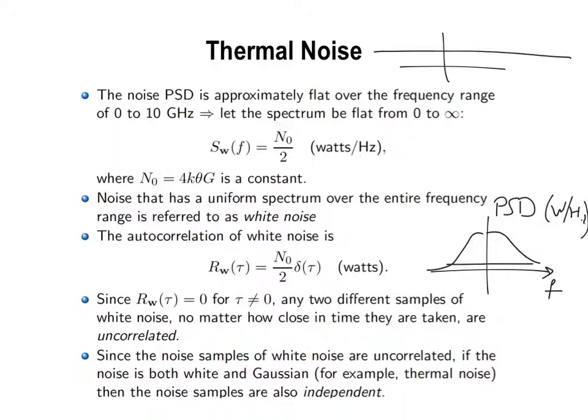So the total power contained in noise is infinity. So how come any of our receivers work? Because our receiver works with a specific value. Exactly. So we are band limiting. Basically, at the input of every single communication system, you have to have something called a band pass filter, which is working around your carrier. So this is your FC, and with the bandwidth of the signal that you are interested in, so some W, around the center frequency.